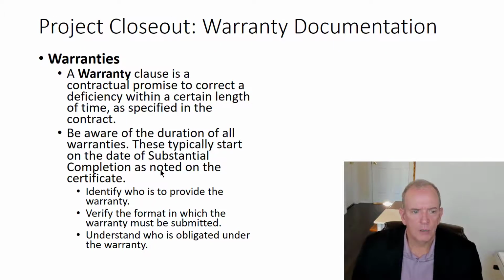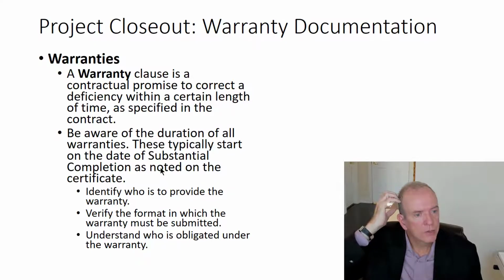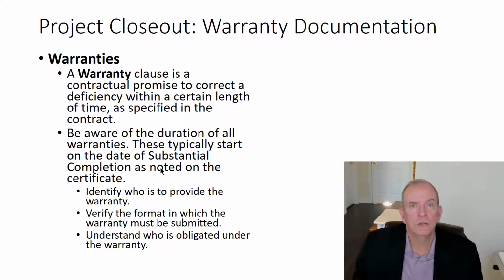You've got, like I said, the warranties, when the warranty starts and when it finishes. Typically the warranty period starts at substantial completion because the owner's using it for its intended purposes. And if it's 1 year, then that's the time period from then to then. That's another reason why it's important to get to substantial completion sooner, because if it takes you 6 months longer and you've got certain things installed, the manufacturer's warranty may have expired, but your warranty has not. That could be a problem.